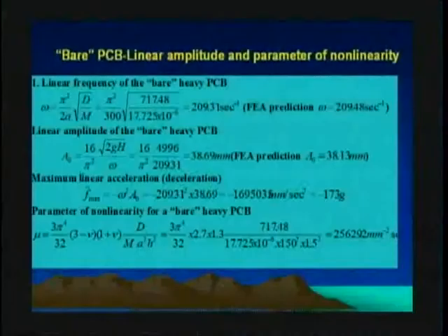What would have happened if we wouldn't have reactive forces? And the finite element confirmed what we confirmed analytically. Yes, it would be very close. Maximum linear acceleration, we calculated that, 173 Gs. The parameter of nonlinearity for a bare heavy PCB is huge, whatever it is.